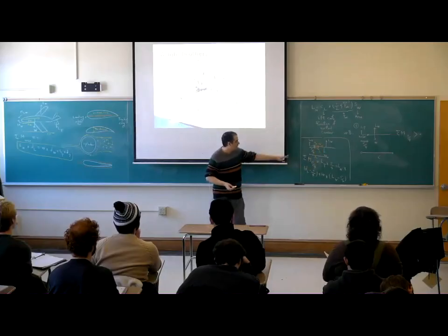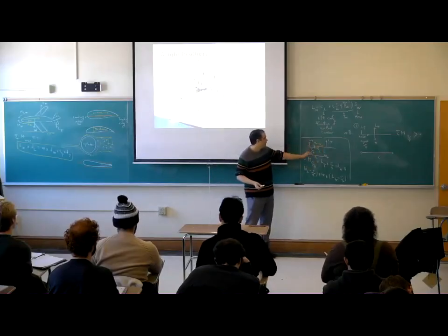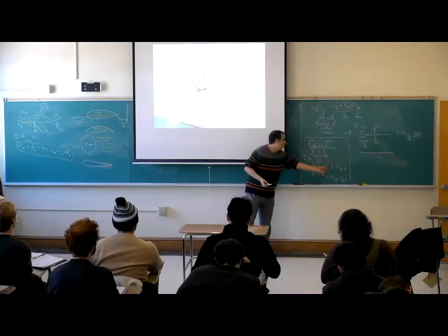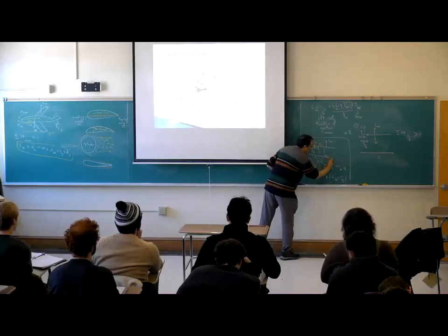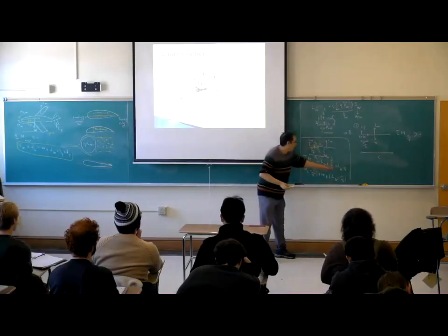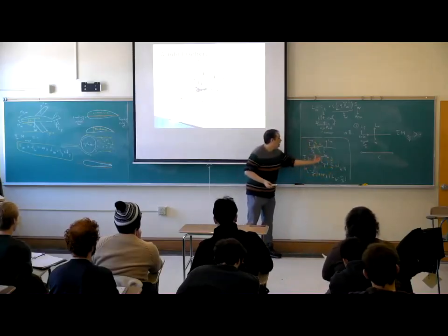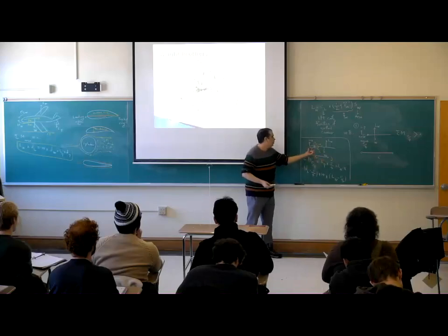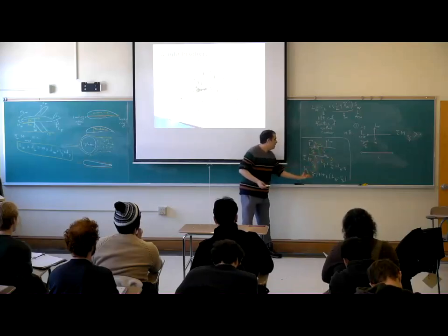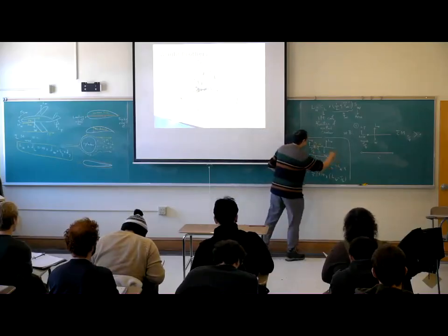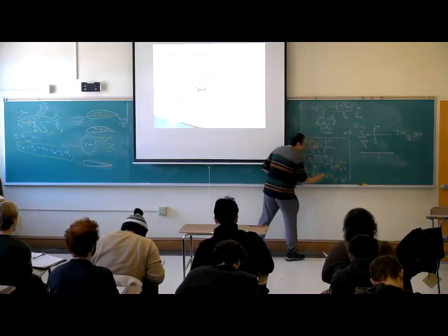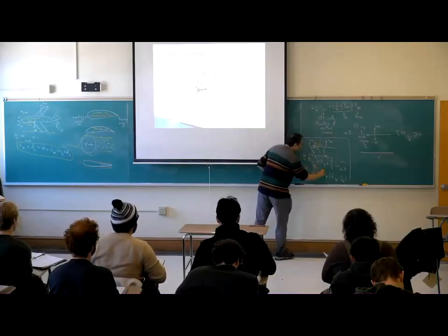So let me explain. Lift of the tail multiplied by 3/4 gives a clockwise moment. Lift of the wing multiplied by d of the L minus c/4, the arm, gives a counterclockwise moment. Weight gives a clockwise moment.